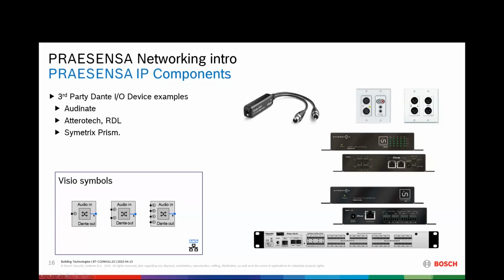So if you want to have an analog audio into the system, you could, with an Ethernet cable, connect this to, for example, port 1 or 2 of the MPS, the multifunction power supply, and then you have already here your two analog audio inputs. So that's the way how you can easily insert analog audio into the system.